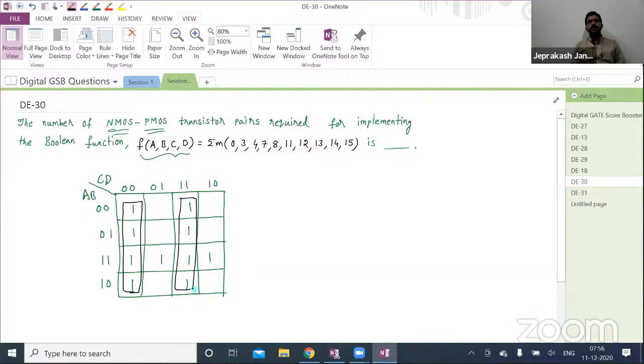Here for this particular K-map, there is the possibility of grouping 4 adjacently placed ones. So do all such groupings. So regarding this, what is the term? Yes, very good, Michael. So horizontal grouping, row-wise grouping, you will get AB. Here C bar, D bar. Here CD. Just 1 second. C bar, D bar. Here CD. Yes, very good. Yes, Srinivas, Michael.